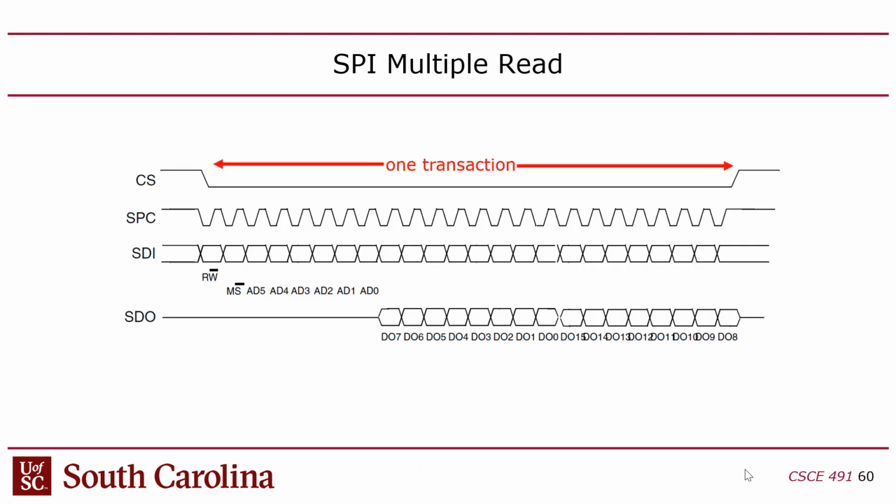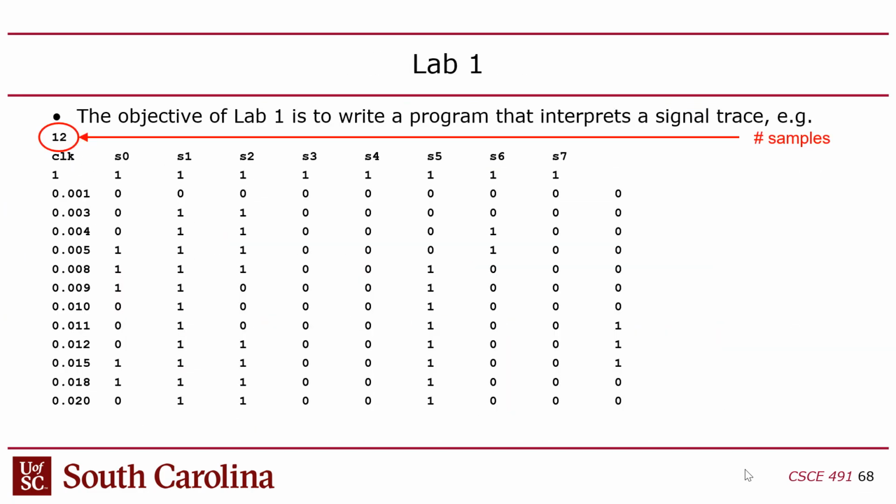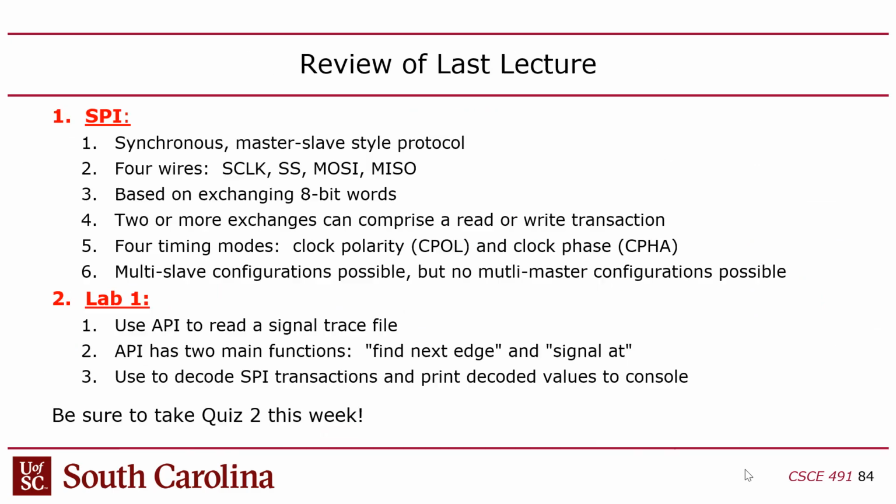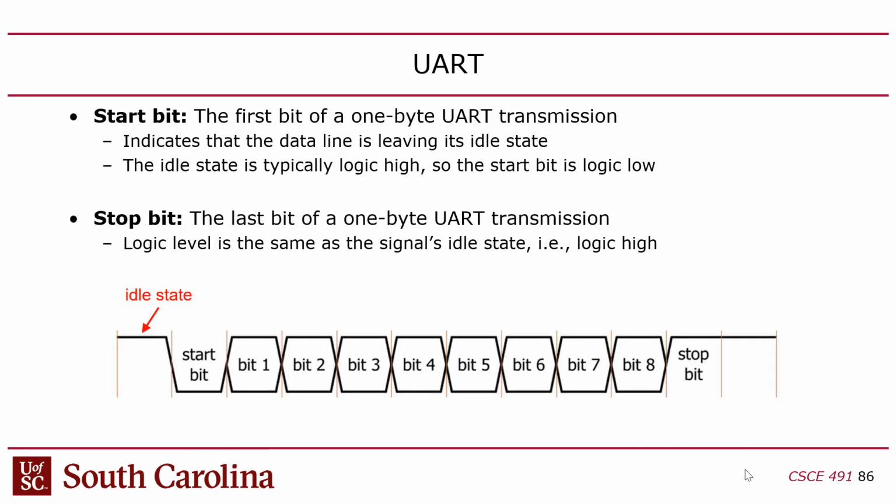And then we got to I²C. Oh, we talked about UART first, actually. So UART uses the start bit and the stop bit, and it's generally used. It's slower. And it's asynchronous. So both sides have to agree on a clock frequency. The problem is that there's no way for them to agree on a clock phase. That's a big problem.